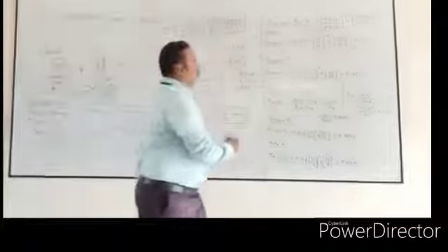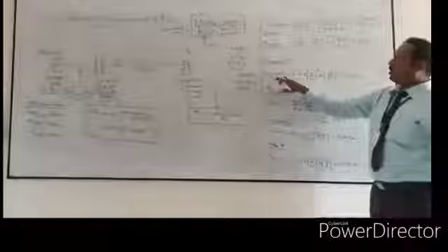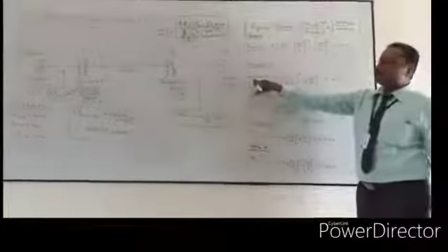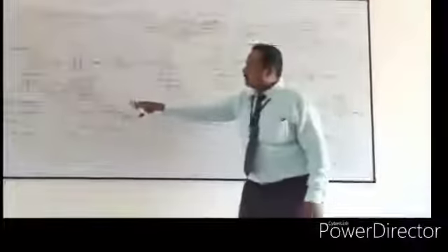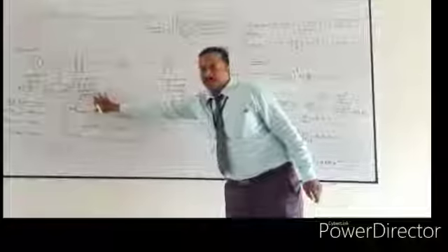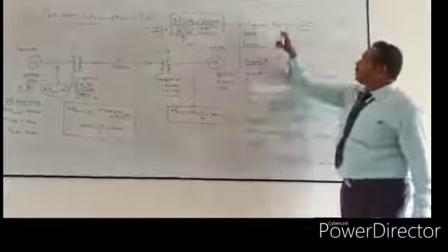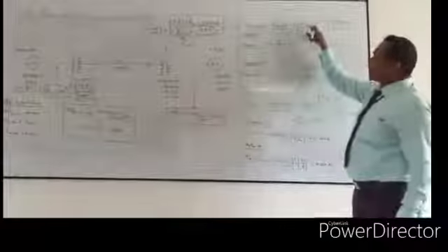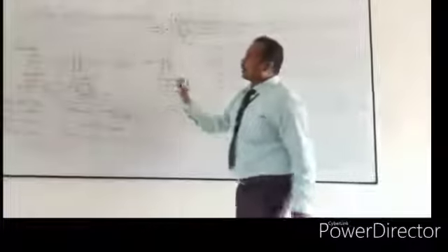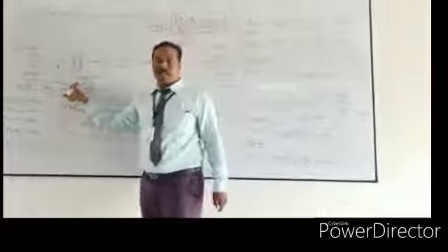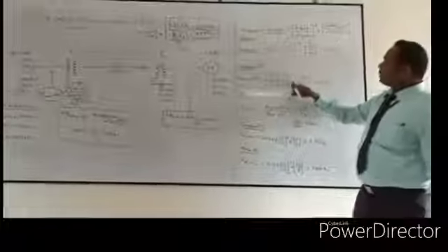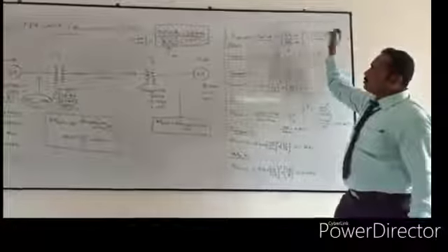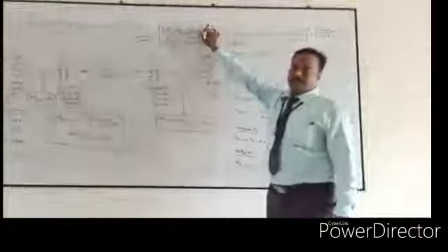Now we can come to the formula. X per unit new, which is transformer 1's new per unit value for the reactance, is equal to the old value presented in the nameplate, 10%, so 0.1. This is the old per unit value. And what is the kVp, the voltage present on the primary side of the transformer? The kVp value is 11, so that is presented here as 11 by 10, where 10 is the kVp new value, multiplied by the new MVA, which is 30 MVA.